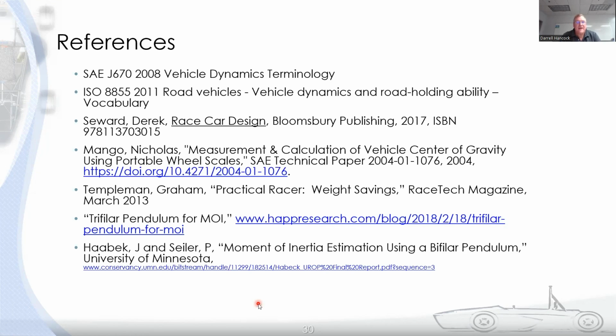You're going to have to break it down into different pieces and calculate the inertia of different parts of it. So that's always going to be an estimate, and there's always some room for error in that estimate, unless you go to a lot of trouble to measure the inertia using something like a trifilar pendulum. So inertias will be a little tougher to accurately calculate.